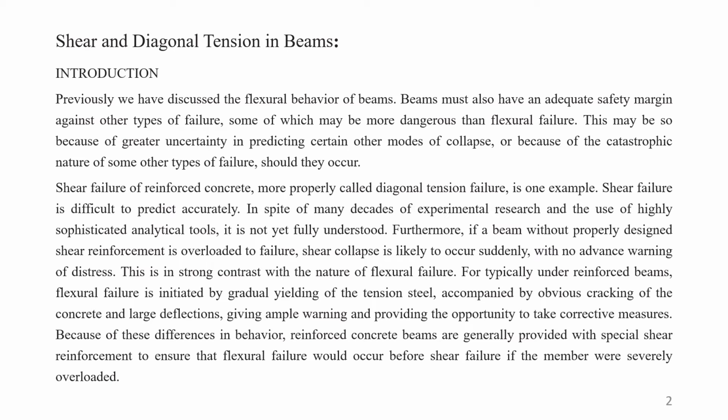And in shear we will be providing the section depending on the strength of the material and the shear force that is to be taken care of by this concrete section. In reinforced concrete we take care of shear by two materials. Some part of the shear is taken by concrete and some part is taken by steel, like the bending moment, where we also use these two materials combined for taking compression and tension.